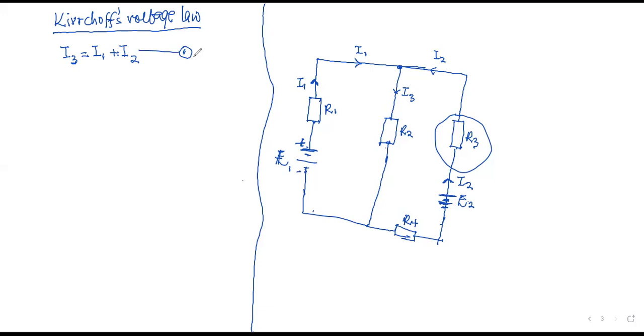This is equation 1. Now you must choose. The second method is that, first, we assign directions to the flow of current. Then second, we apply the junction rule. So assign direction of flow to current, and apply the junction rule. The third method is that you derive as many loops as you can, or obtain as many loops as you can from the circuit.